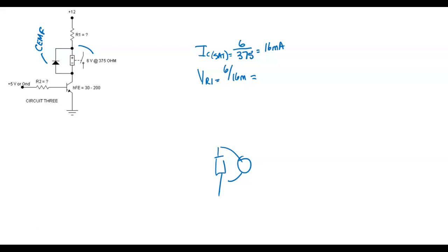Okay. So here we give you the ohms, but you'll see this all the time. Like your car, you got a 12-volt relay. It may or may not have the ohms on it, right? All you need to do is use your ohm meter, and you can actually find the coil. If you don't know where the coil's at, you can start moving around the pins, because your contacts are either going to be normally open or normally closed. So a contact is going to either measure infinity or almost zero ohms. And when you find ohms, then you found the coil.